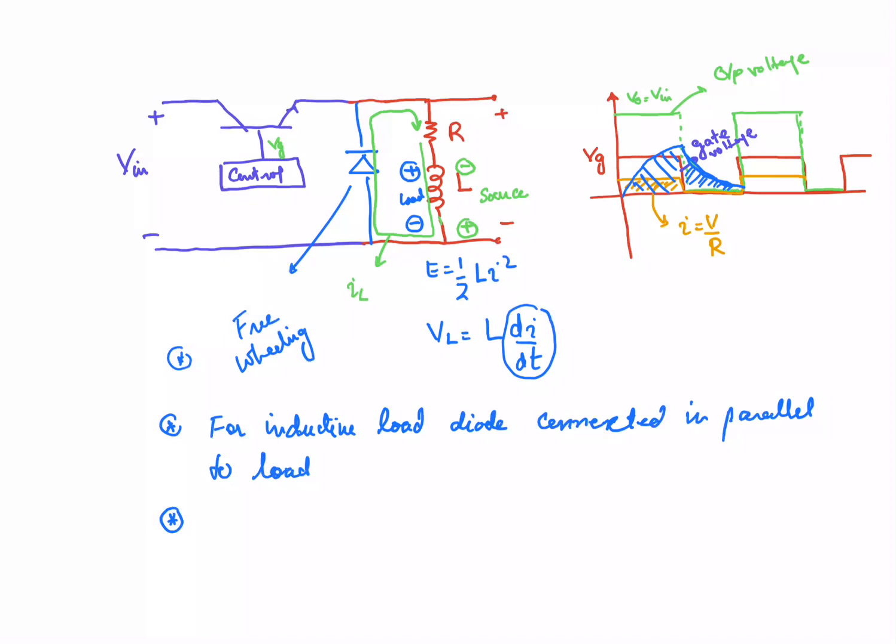Okay, one more thing that is important to be considered over here, that this diode will be turned on in every cycle. So you operate usually your converter circuit at the high frequencies, so you must use the diode which is operable at the high frequency. So it is a high frequency diode. General purpose diodes cannot be used over here. So it's a high frequency diode with very small TRR, reverse recovery time, so that you can switch it immediately and turn off immediately as well. So high frequency diode is used which has very small value of the recovery time.